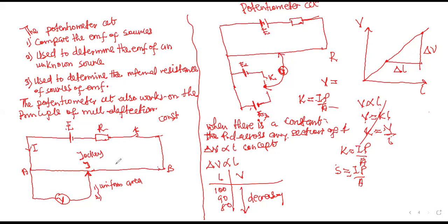Don't forget that under this experiment, the concept is that when constant current flows through the circuit, the voltage drop across the length of the conductor is directly proportional to the length. So as you are scratching, it generates heat, and heat would change the resistance. When the resistance changes, it would affect the constant current which must be maintained so that the experiment will take place successfully.